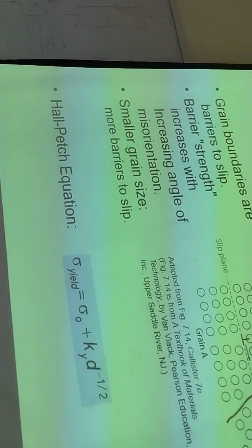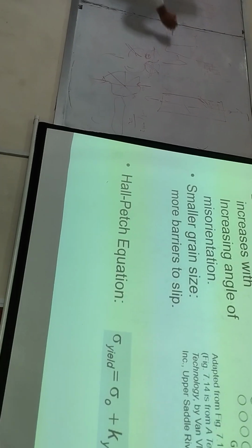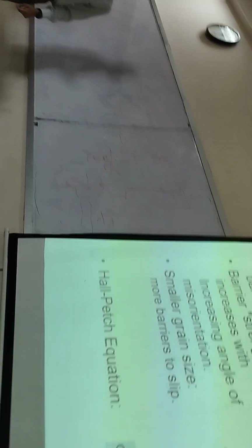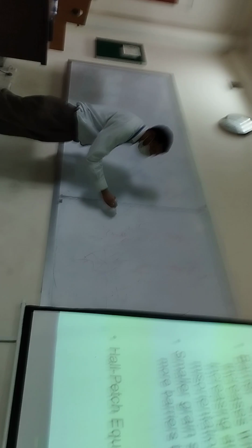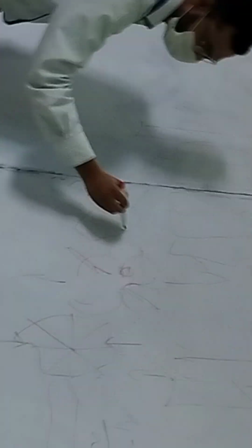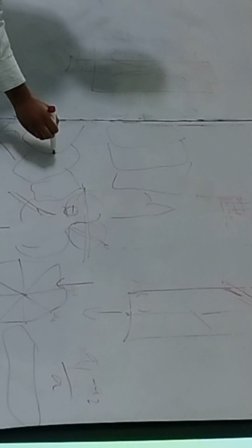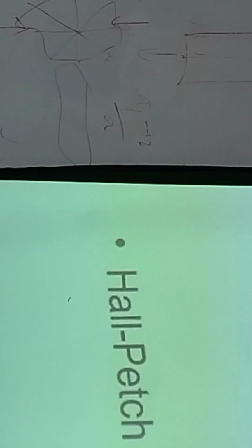So when we have grain boundaries, if grain boundaries are like this, it is going to lead to less strength as compared with if we have grain boundaries like this, oriented at random. This boundary is at some other angle, over here it is at another angle. So these angles are going to lead to a dampening effect on the movement of deformation. Force acts along the x-line.